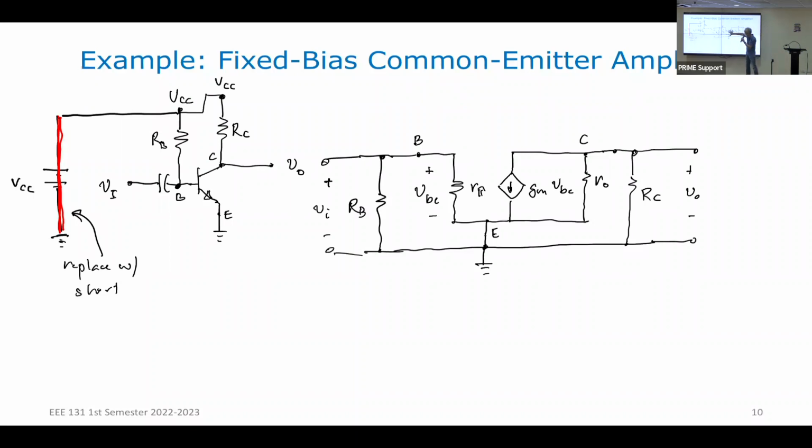So this is now the small signal model of the entire circuit. This is the small signal model of the transistor. I have now incorporated the small signal model of my other components. So now I can determine the hybrid pi parameters of my entire circuit. Let's start with GM. What is GM? You better start familiarizing: GM is output current divided by input voltage at no load.